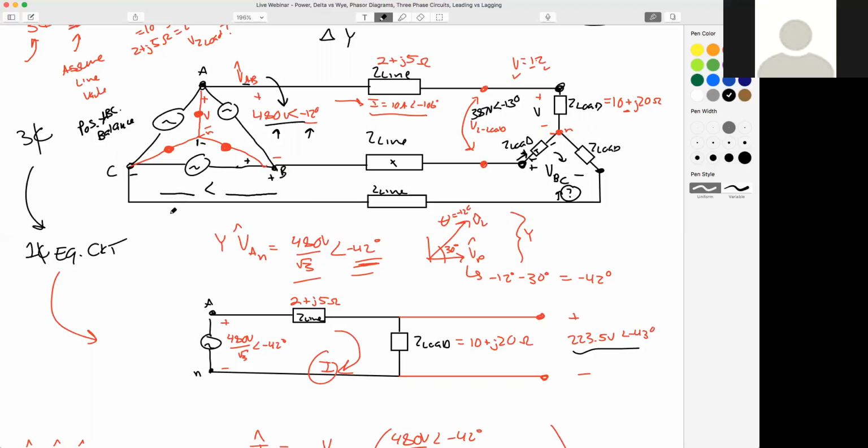What would my magnitude for VBC be? So this is VBC, which is really our B line voltage. Magnitude would be, yep, 480 volts, Alex, and you said minus 132. So minus 12 minus 120, that would be negative 132 degrees. Careful, Greg said 102. Careful, Greg. Alex, you got it. And Omar, yep, fantastic. Great job, Omar.